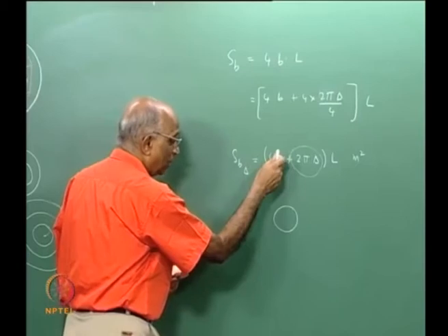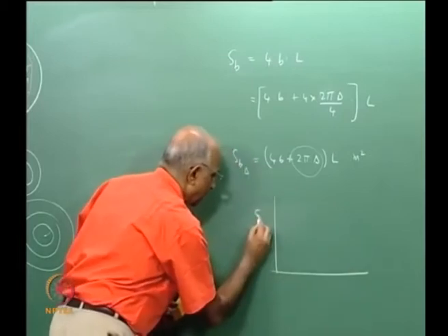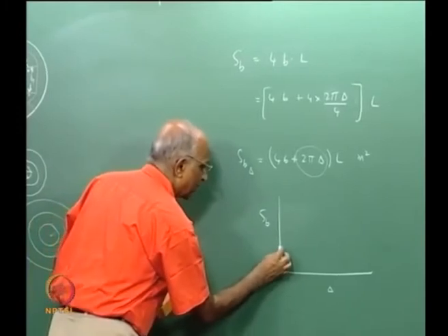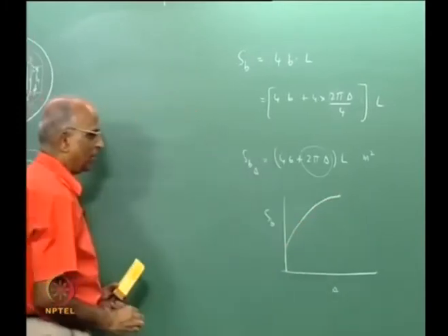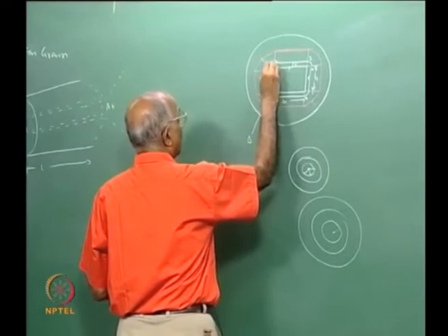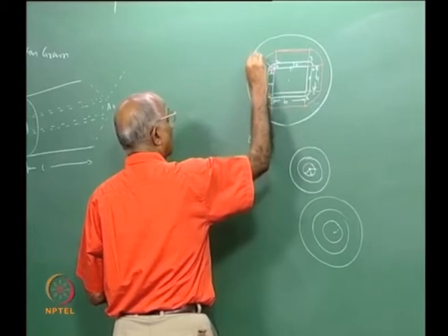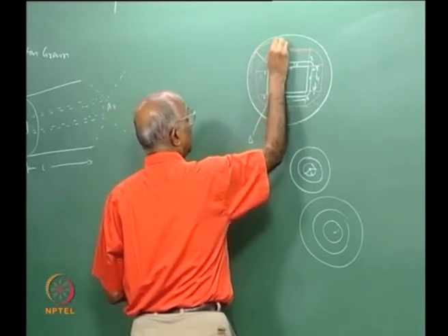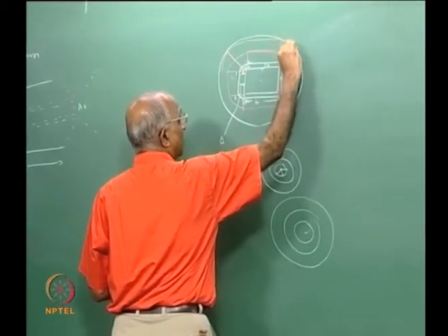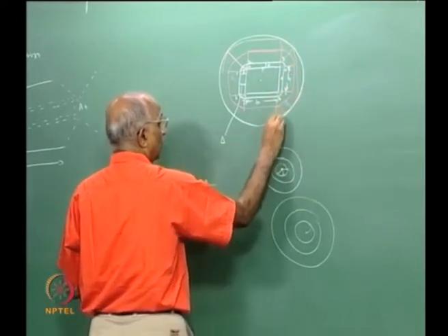in this case I get little effect over here, and the burning surface area would keep on increasing still further as the value of delta keeps increasing, until it reaches this limit. When does it reach the limit? When this particular tip or vertex comes and hits over here, then I have a circle of diameter over here, and the plane surface comes over here, then when this comes over here, again a circle over here, hits over here, hits over here.